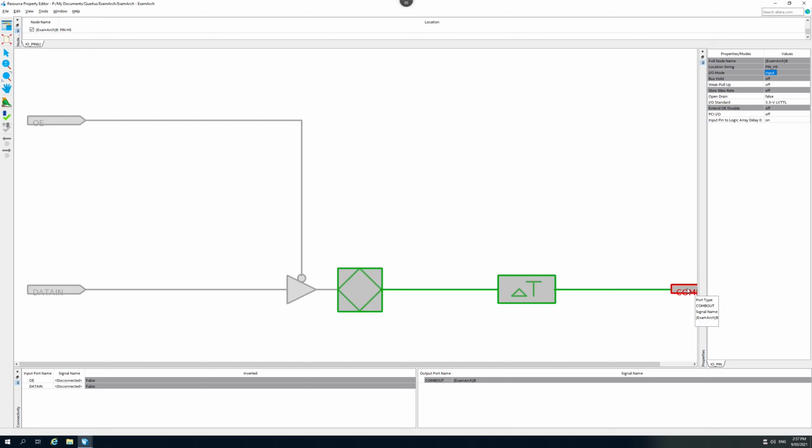Where we see that the signal name is capital B in our Verilog code. It's not using a weak pull-up, we don't need a slow slew rate, etc. These things, if you want to understand them, you look at the user manual for the Max2 complex programmable logic device. The input-output standard says that it's 3.3 volts. So the signal comes in the pin, then goes through an appropriate buffer to convert it from the 3.3 volts that it's configured for to whatever the internal voltage is for this particular FPGA. For the Cyclone 5, I believe it's 1.1 volts internally.